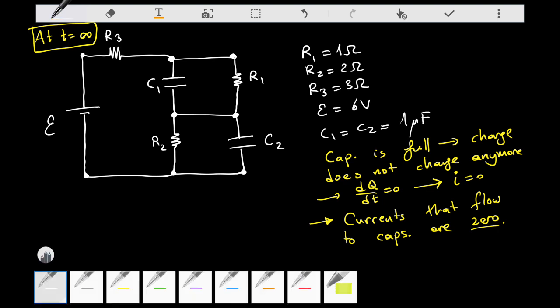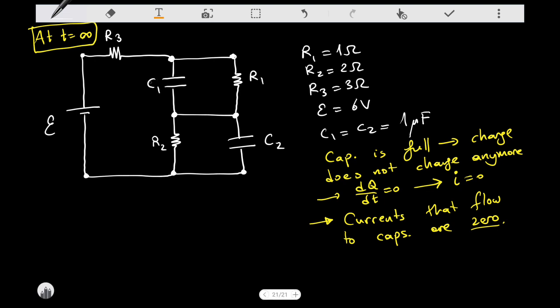Mathematically, this is equivalent to an open circuit situation. So what I would do in that case is to basically remove this capacitor in here, and these wires as well. So as a result, this circuit has the same solution as the circuit where there's a capacitor connected in that region, right? When there's a capacitor in here, I'm going to get the same solution as this circuit, okay? Because there's no current that's passing from here. So let's do it like that. I'm also going to remove the capacitor in here. So this circuit has the same solution.